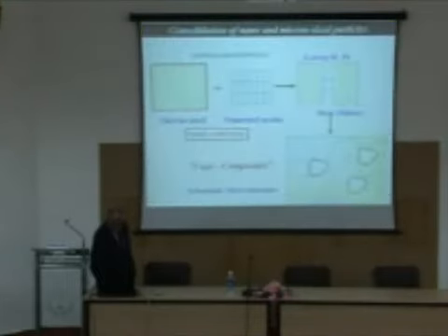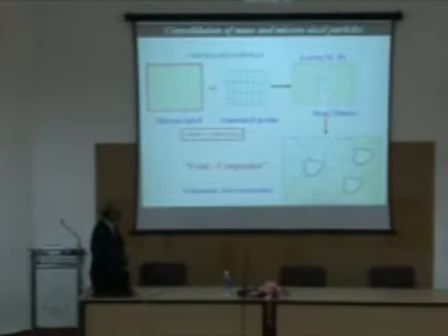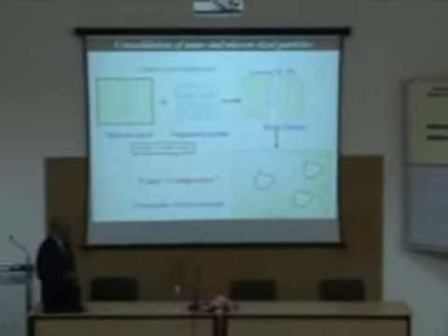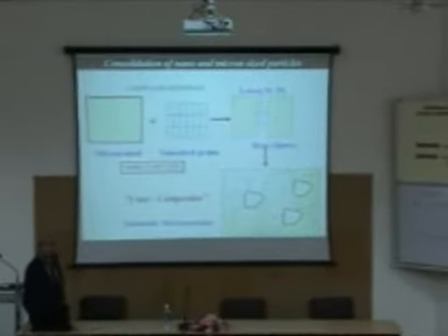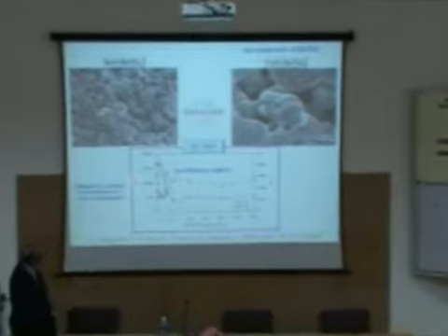One thing we did was we tried to enhance the properties of a micron-sized, normally used barium titanate using some nano-sized grains. And because the nano-sized grains will have a lower melting point, it would fuse the micron-sized grain. This was the model. So we made what we call N-mu composites, nano-micron composites, and we were successful.